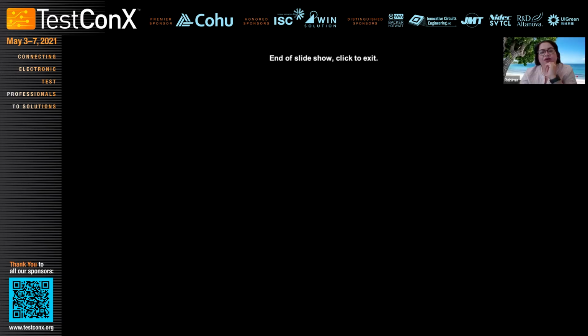Which one are you recommending here? Is it a gold-plated or is it the homogeneous? For a spring probe socket? No, not for spring. I'm not talking about spring probes. Yeah, so this is the elastomeric sockets. With elastomeric sockets, we only have the gold powder suspended in silicone, which is typical. So there's no homogeneous elastomer that I'm aware of.